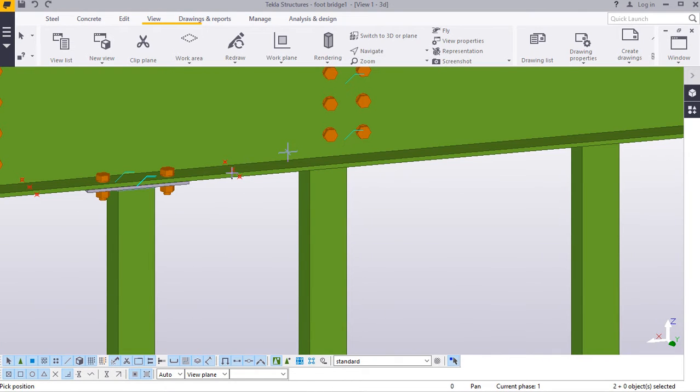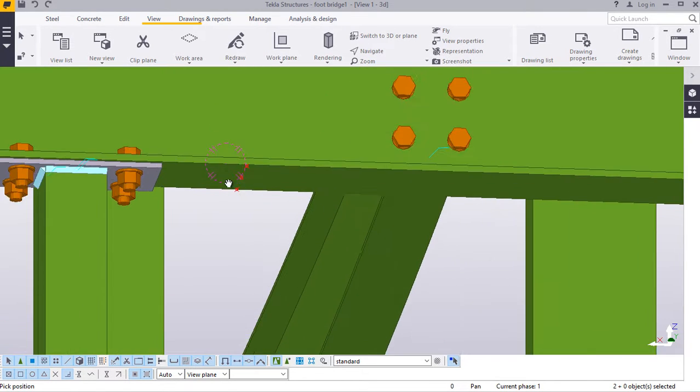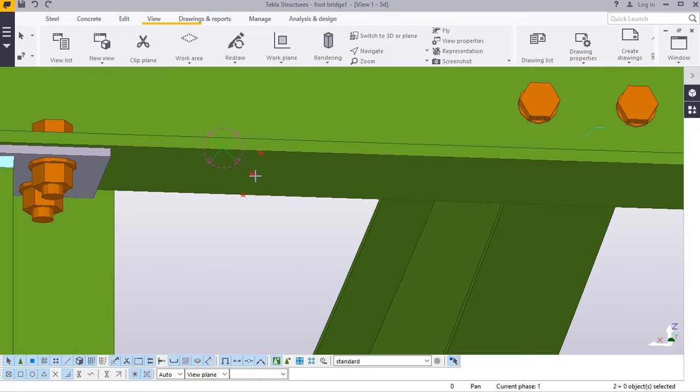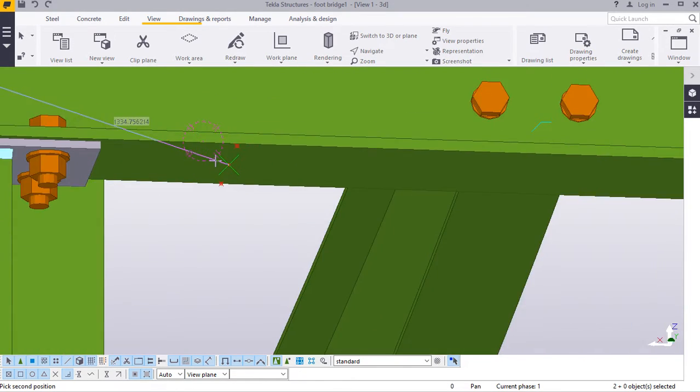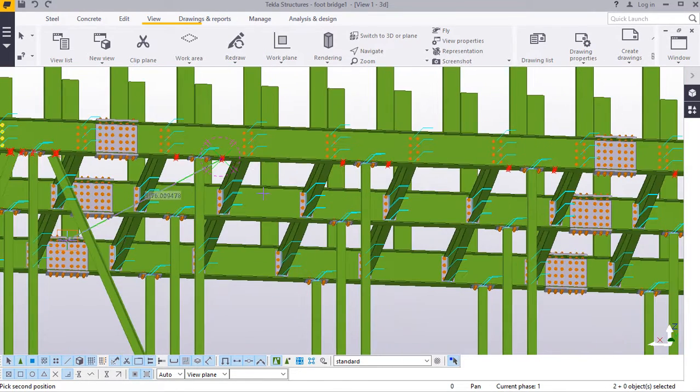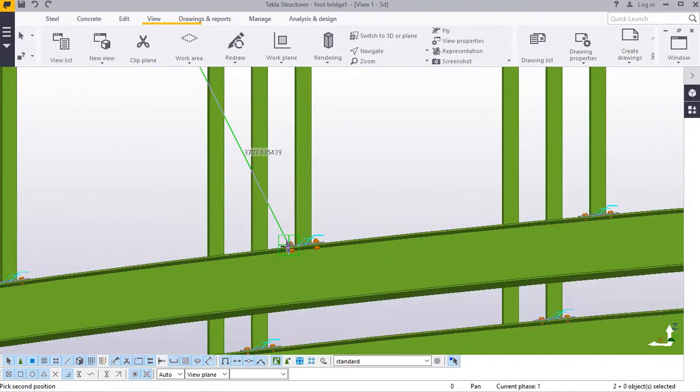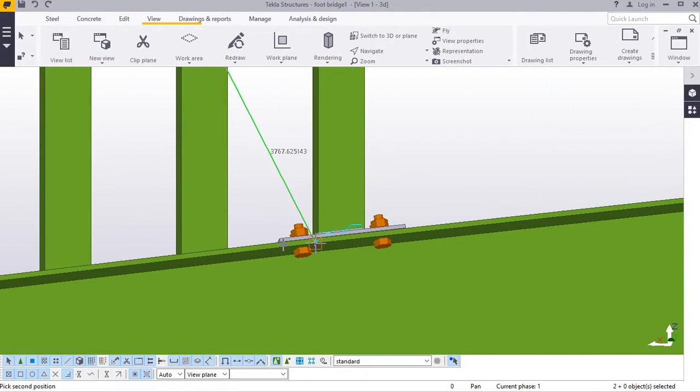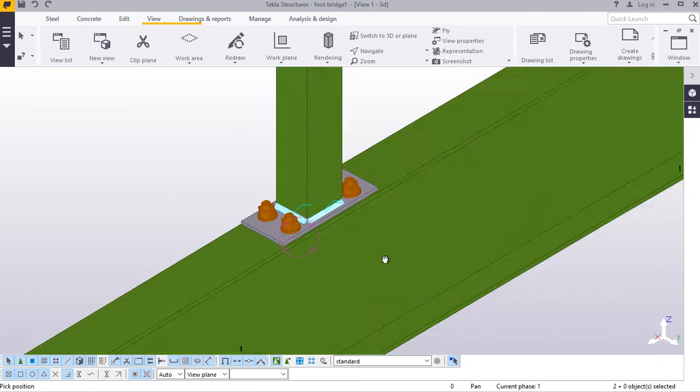We'll come to navigate, rotate with mouse, rotate about that spot. Right click to disable that command of rotation, and I'll click behind or right on that spot. I'm unable to see the place or the point I want to locate the bracing. What I'll do, I'll come to navigate, under view, rotate with mouse. I'll rotate about this spot. Once you've picked, press your left button on the mouse and hold and turn round like that.